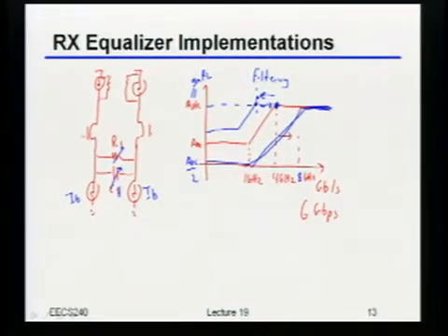things that have first order responses, meaning that they could fix a channel that has a first order roll-off. Bad news is most channels have much higher order roll-offs than that. Oftentimes at least like 2 poles. Okay? So now what I'm going to want to do is figure out, okay, how can I take this equalizer and potentially add another pole? Or excuse me, add another zero.